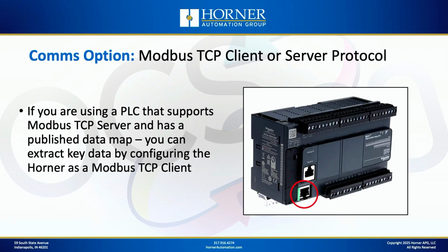The next one we're going to talk about is much more general purpose, and that is Modbus TCP. Many PLCs support the Modbus TCP server protocol because they need to be able to be polled by things like SCADA devices and those sorts of things. By far the most common protocol used for that purpose is Modbus TCP. So the Horner, when used as an edge controller, of course, has support for Modbus TCP client, and we can poll a PLC that's running Modbus TCP server.